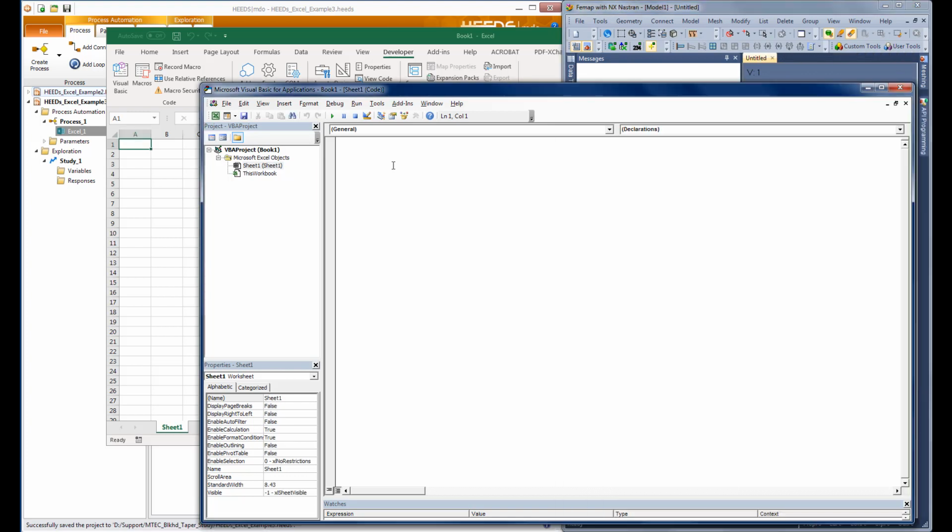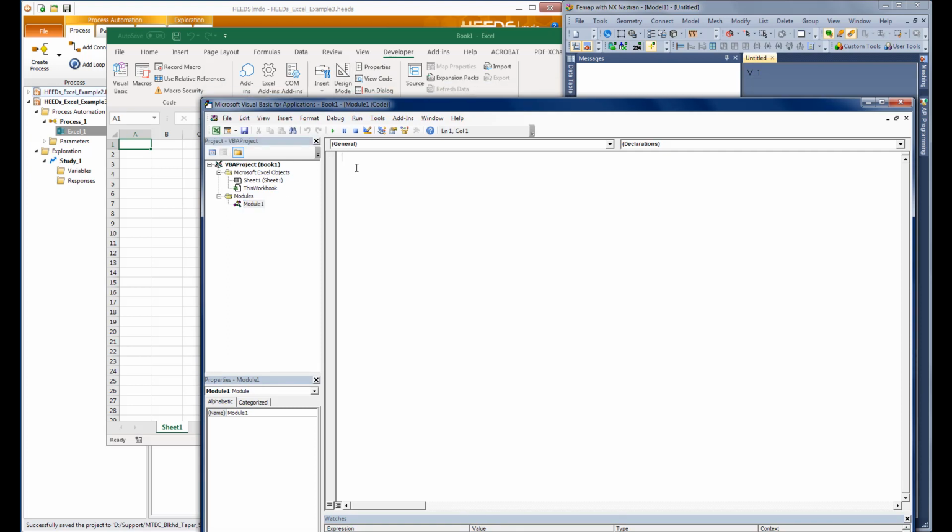So when I'm in Microsoft Excel, what I can do is use a GetObject, which you may or may not be familiar with. Before I do that, though, I'm going to insert a module here, just because I prefer to work with modules in Excel versus Sheets. Sheets will run code on a sheet. Module, you can call it from buttons in Excel that you add, or you can call it more appropriately with different macro titles. So I'm going to call this sub FEMAP, and I'm going to say dim app as object, and then set app equal to GetObject, comma, FEMAP.model.